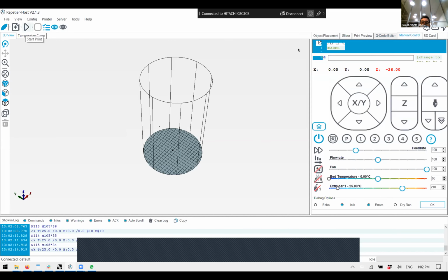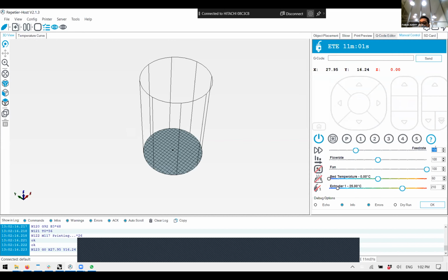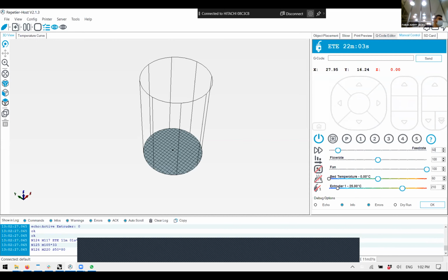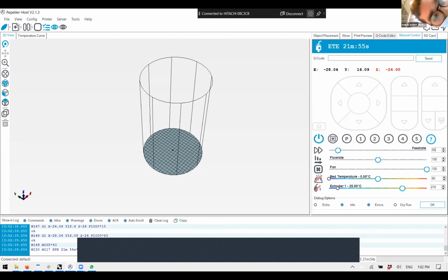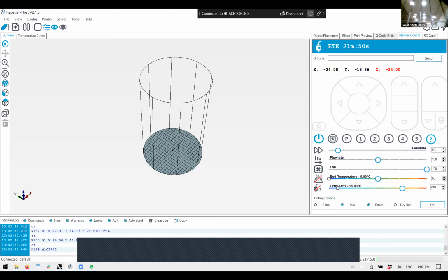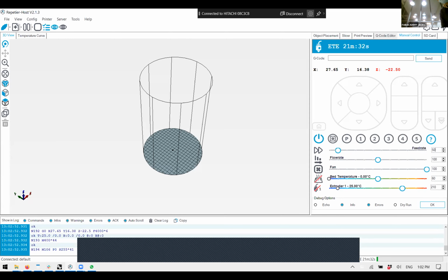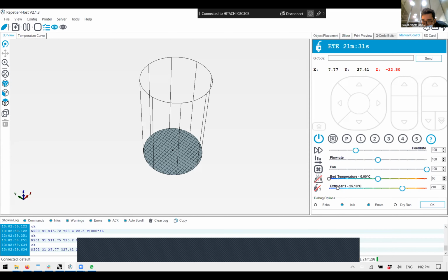Let's try to print. In manual control, I will set the speed; let's start at 50% of the speed, because I need to calibrate the amount of pressure so it flows enough material for the speed I'm using. It has pressure, but you see it's too much pressure. I have to reduce it so I don't print too thick, because I didn't test it before. The first time, the first value is usually, let's put it at 100. So now it's no pressure.